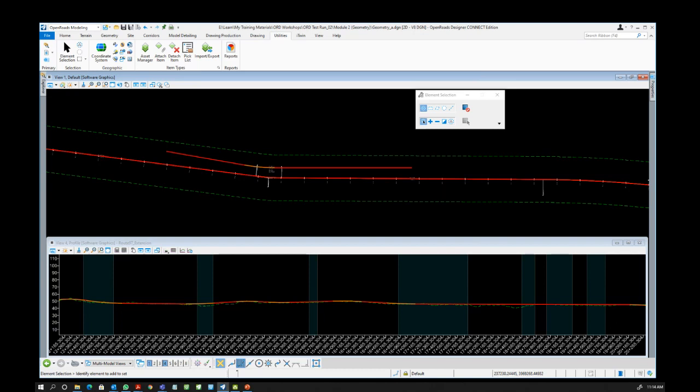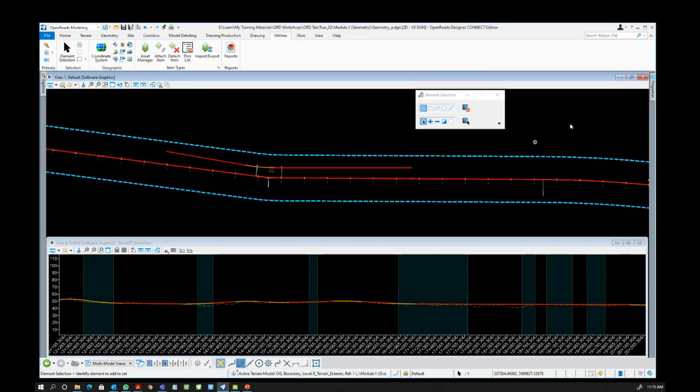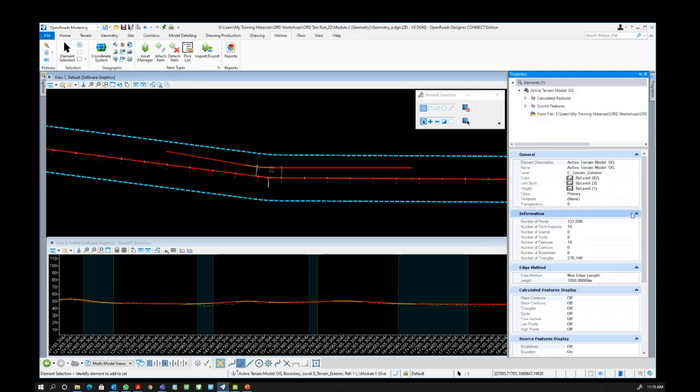Next, when we imported the OG file, the boundary will be created automatically. Yeah, of course, it will be automatically created, because basically how it was created from the other software, it already has its own triangulation method, right? So once imported in OpenRoads, depending on the feature definition you use, it will inherit the boundary. But sometimes, if you change the, remember, this is just a reference, that's why it will not allow us to change anything.